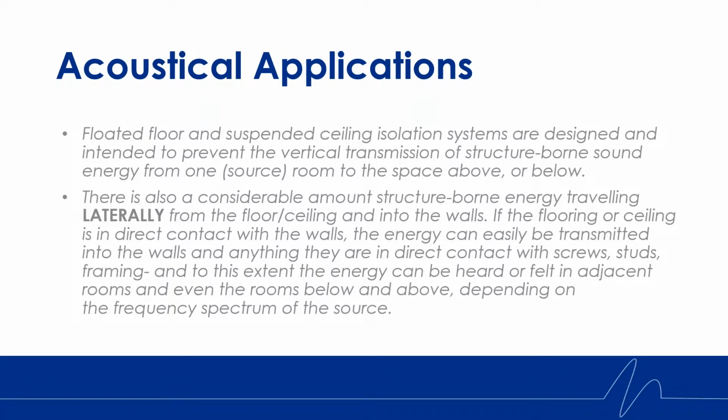So if the floated floor or resiliently supported ceiling is in direct contact with the walls, the energy can easily be transmitted into the walls and anything else they're in direct contact with. So screws, studs, framing, all components of that wall. And to this extent, the energy can be heard or felt in adjacent rooms.